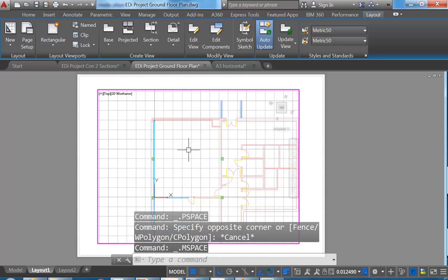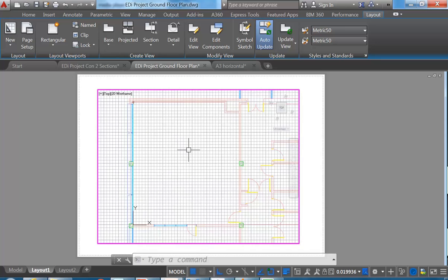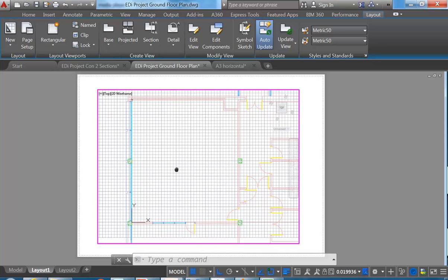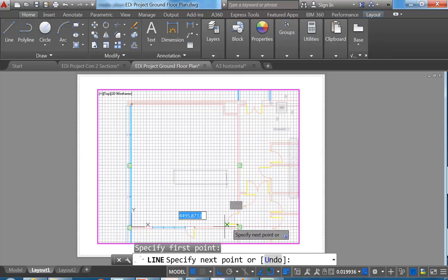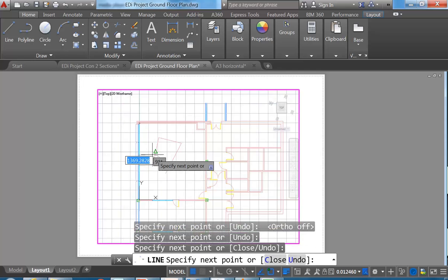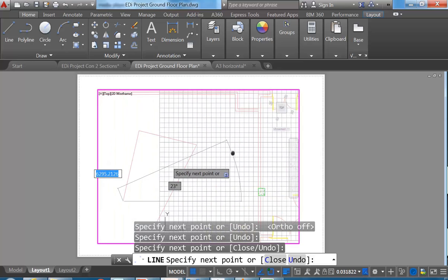And then when you're in model space, if you zoom, it'll zoom just inside the viewport. If you draw something, it draws it again in model. So just draw some lines here. So if I zoom, those lines are going to get bigger and smaller, and they exist only inside the viewport.